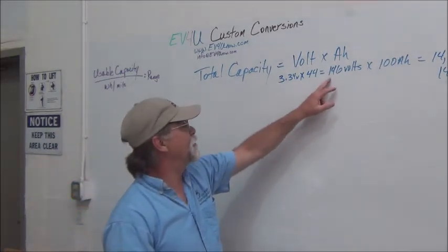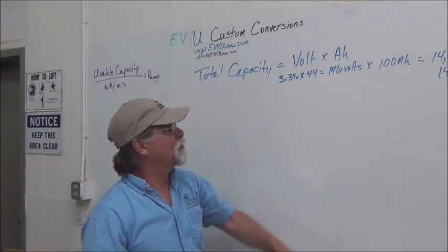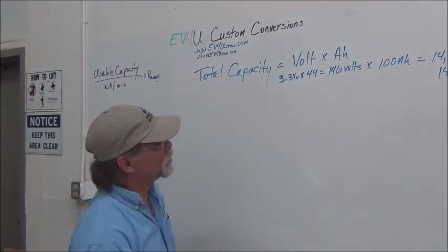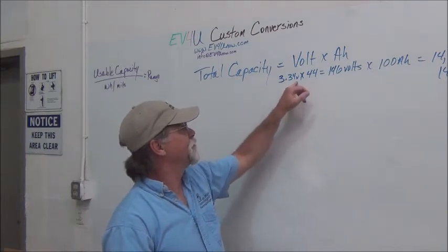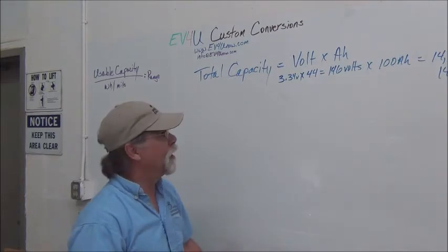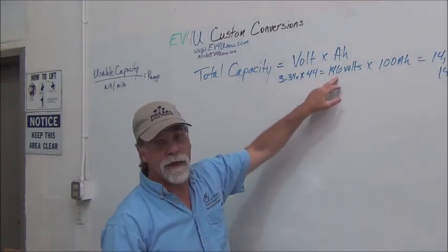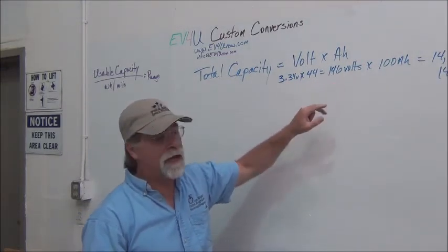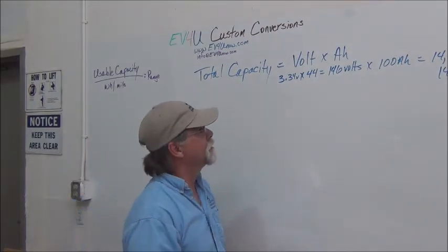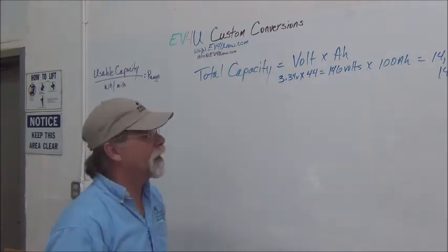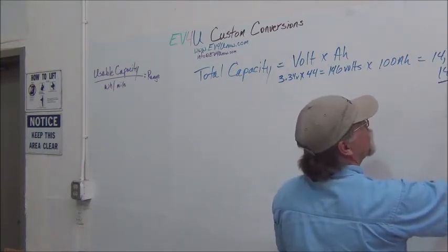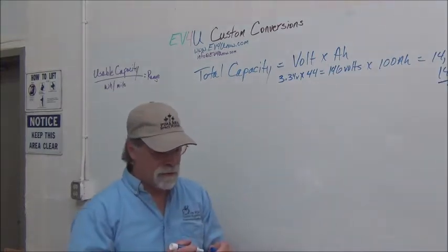This actually comes out to, I think, 146.9, so it'll be 147 volts. This depends on what you want to use for that nominal voltage. Because we do a lot of these 44 cell packs, I know that the nominal voltage is basically 146 and change. So that's why I'm using that number, okay? So this then is our total capacity.